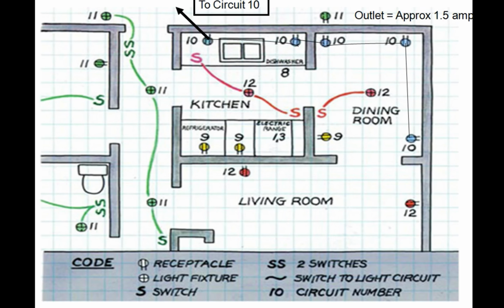Right, this is a typical engineering or even a field layout sketch. Alright, that just kind of gives you an idea of what's where and how it's connected. Okay. You'll see which circuit breaker everything is aligned to, and we talked about how you can have a number of different outlets or prongs or lights connected to each particular circuit breaker, as long as you're not overloading that particular circuit.